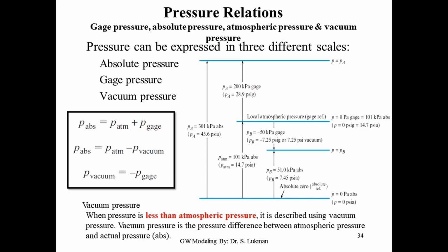This is the total head, which remains constant throughout according to Bernoulli's equation. The pressure head is here. If you add the elevation head, this is the piezometric head.